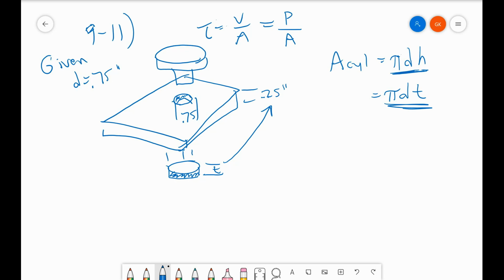And it says the ultimate shear strength for aluminum is equal to 27,000 psi. Ultimate shear strength is the shear stress you have to apply to cause it to break, or in this case, to punch through. So we rewrite our equation, and we have shear stress equals load over area, and we're trying to solve for the load. We know what the shear stress is, that's given in the problem statement. The area we can probably calculate.